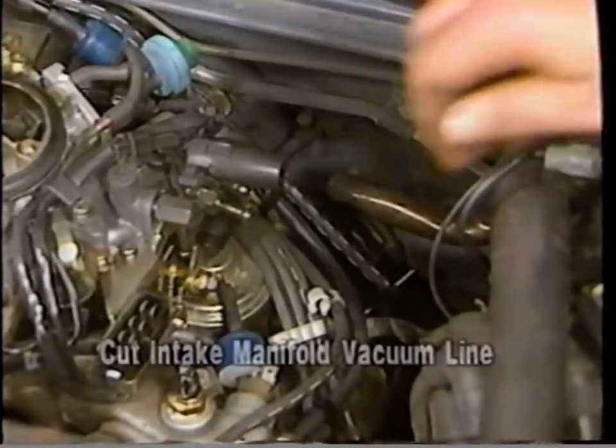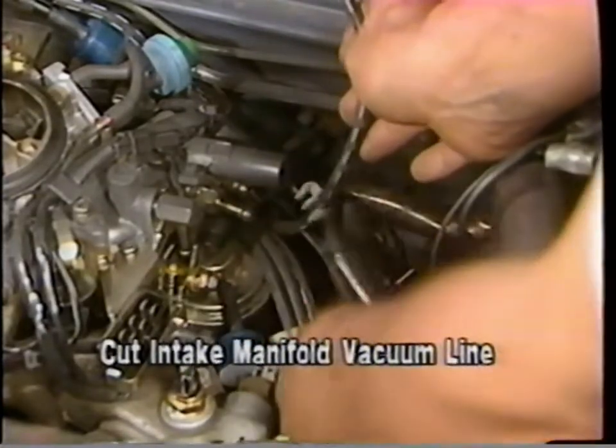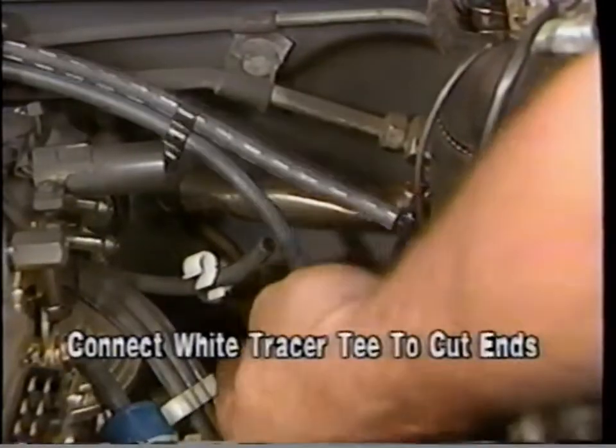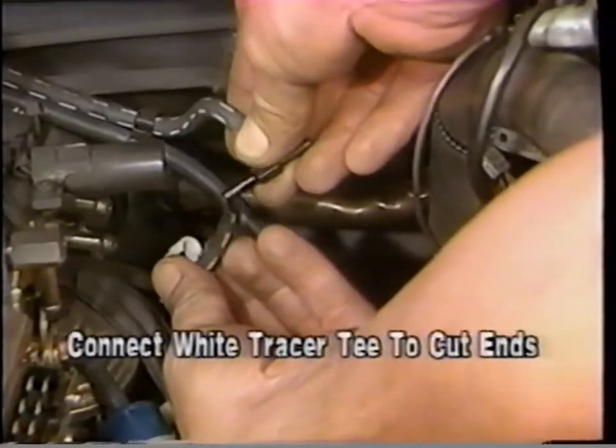Locate the vacuum line from the intake manifold, which was plugged earlier in this procedure, and cut the line as shown here. Insert the harness vacuum tee at the end of the white tracer hose into the cut ends of the line.